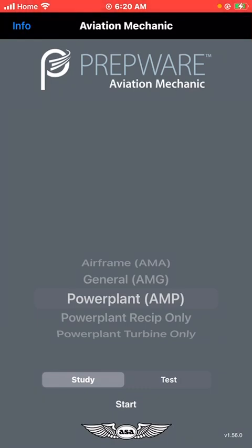Which of these characteristics are desirable in turbine engine oil? High flash point. The purpose of directing bleed air to the outer turbine case on some engines is to provide optimal blade tip clearance by controlling thermal expansion.